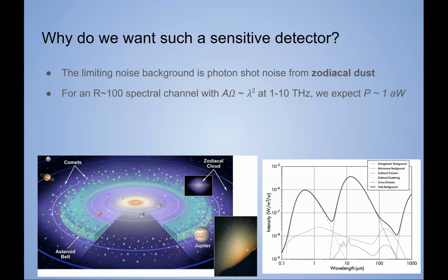Yeah, I think some insulator, some oxide. I don't think anything in the silicon matters. The silicon wafer is basically what we print everything on, and then we put our aluminum, our niobium, our dielectrics on that. I don't think the silicon substrate itself matters that much for the noise performance. The only reason I can think of it mattering is if a cosmic ray comes through your wafer, and maybe other materials would propagate phonons or energy differently. But I think silicon is just pretty standard.